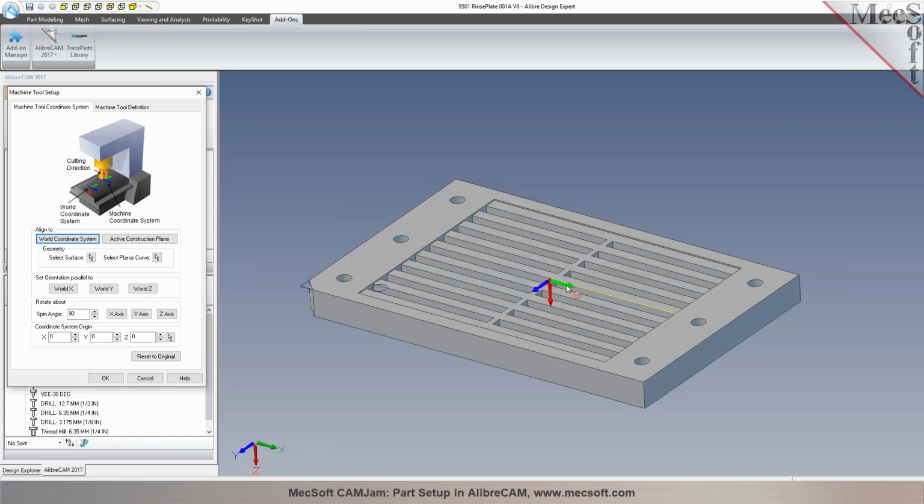Okay. So you can establish your X, Y, Z axis orientation. In this particular case, it's just a rotation of 180 degrees on the X-axis. So I can type in 180 and then rotate about the X. You will now notice that the Z-axis is pointing normal to this face. Now I could have also selected a surface and picked the face. It'll use the normal orientation of the surface to orient it. Or you can use these spin controls in here to establish that.